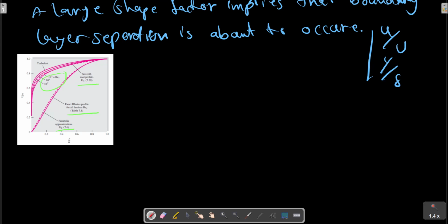Instead of decreasing parabolically to zero, the turbulent profiles are very flat and then drop off sharply at the wall, as shown. As you may guess, they follow the logarithmic law shape and thus can be analyzed by momentum integral theory if this shape is properly represented.